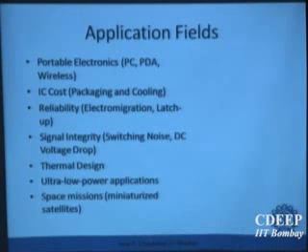There are issues in integrated circuit design. One is called reliability. If I make a circuit, reliability means it should work on given specification for a given time. Let's say it is a reliability of 90%. So you say this is designed for 5 years: 90% of chips will work for 5 years. If the system does not remain reliable after some time, then no one will buy from me.